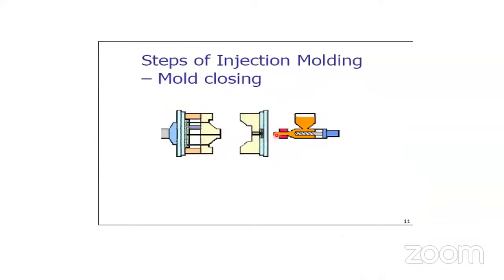And therefore, friend, always remember the cavity is fixed on the fixed platen by Allen key or by using a nut and bolt with the help of clamps.